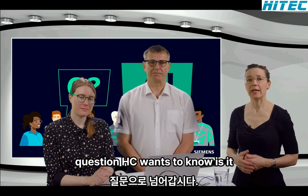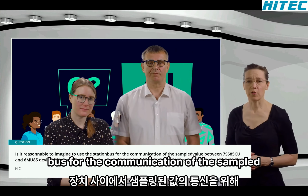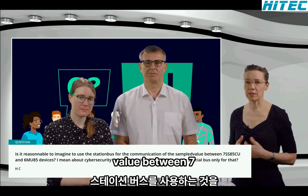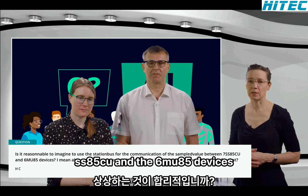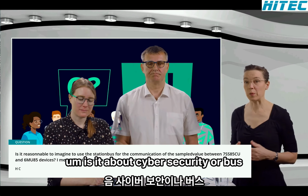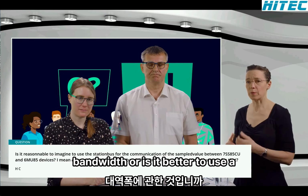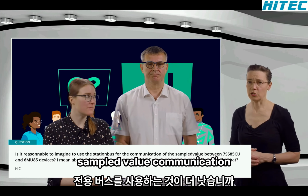HC wants to know, is it reasonable to imagine to use the station bus for the communication of the sampled value between 7SS85 CU and the 6MU85 devices? Is it about cybersecurity or bus bandwidth? Or is it better to use a special bus only for that? So for the sampled value communication.